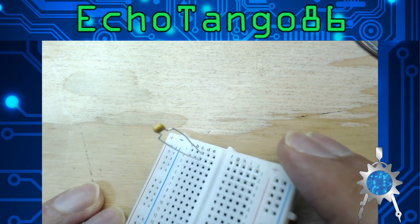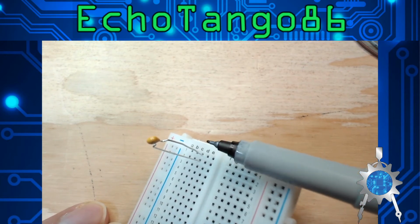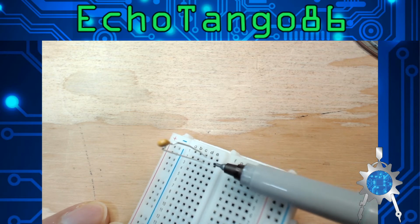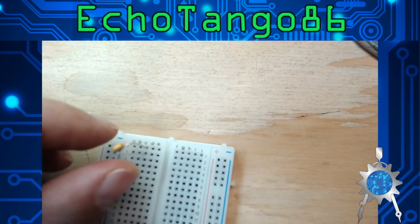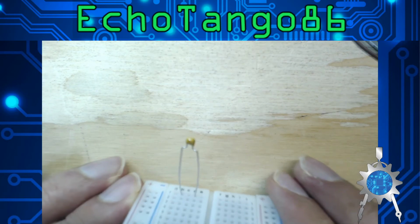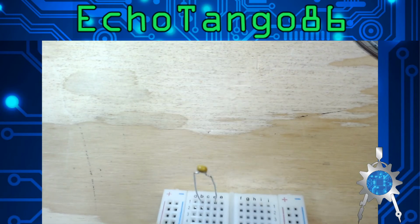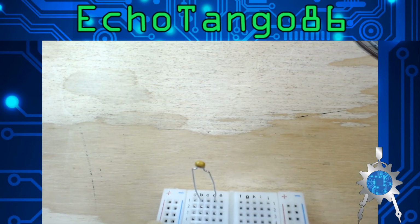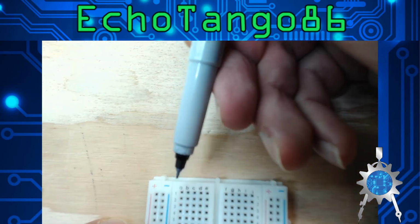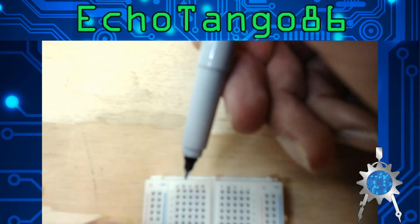If you put it in this way, the two leads aren't connected together. They aren't touching. They're not shorting, because this row and the one below it are not connected together in this direction. They're just separate from each other. But if you were to try to put it in like this, see how it's in the same row? Those leads are connected. They're touching. This is a short. This is not how you want to do it. So it connects this way, not this way. The rows are separate.